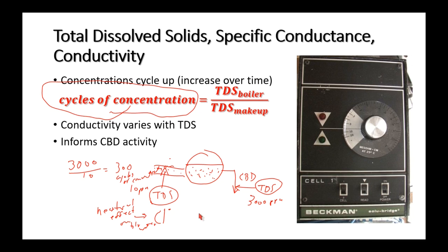Of course, understand it's not magnesium chloride or calcium chloride, which would be scale forming. No, but if it's sodium chloride, it's not going to cause us a problem. So if we measure the chloride ions coming in and we measure the chloride ions leaving, we can more accurately determine the cycles of concentration.